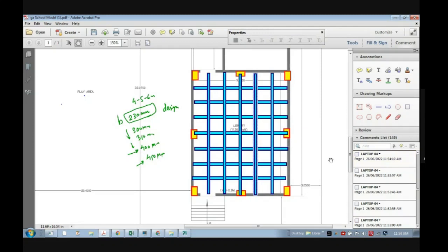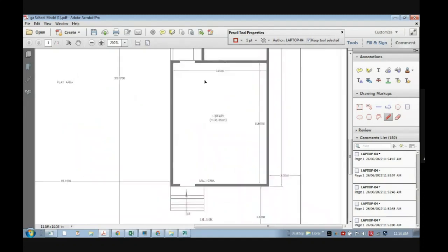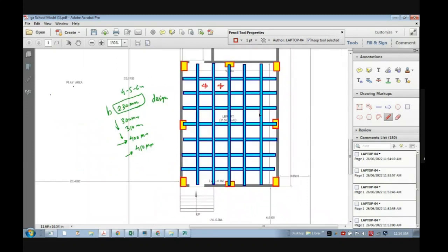So in this case, also beam depth maybe around 450 or 500, it will be sufficient. And then there will be smaller slabs between this. So here every slab is a smaller slab. So the concept is different here. Please try to understand. So this is local behavior, but actually in totality this grid slab is nothing but a two-way slab.